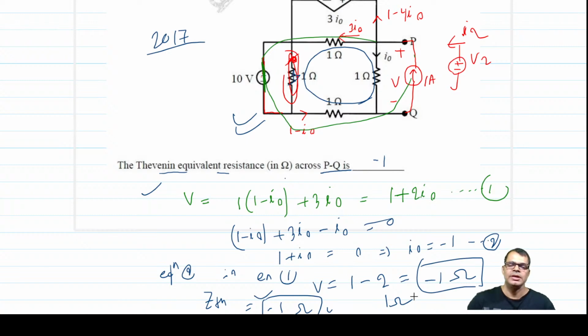They are also useful in the application of oscillators. Negative resistance, we intentionally do the negative resistance so that we can cancel the positive resistance, so that power loss would be 0 in that circuit or minimized. Whenever you do analog VLSI design, when implementing the solid state oscillators, you will learn how to design a negative resistance circuit, so that it can be connected to the oscillator.